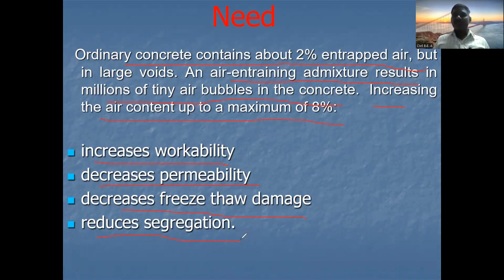So the bubbles will increase, and due to the bubbles the segregation will be reduced and the workability of the concrete increases. Also, we can decrease the permeability of the concrete by adding the air entraining agent.